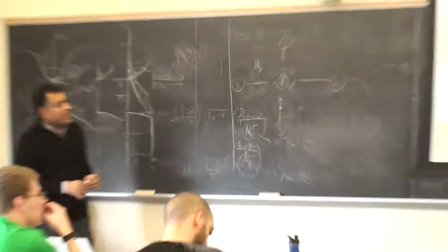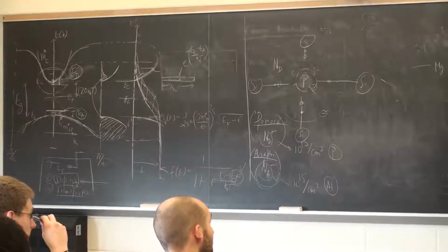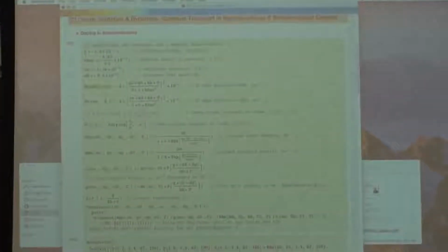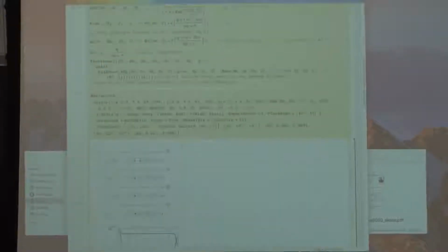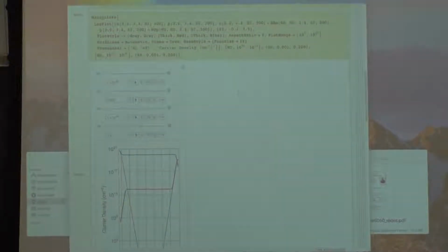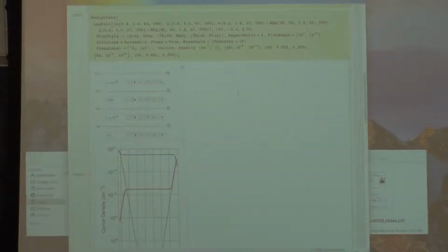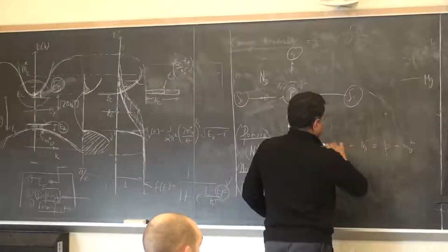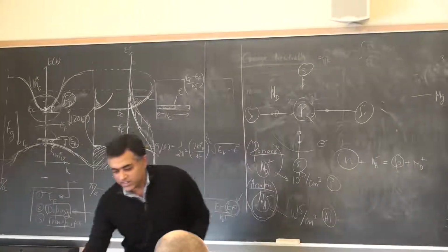One of them is a very deep activation energy, and you can set it up with ND, NA, and so on. Now for any general semiconductor, I can say, plot me the following things. I have 4 terms here: N, P, Na minus, and Nd plus. I can plot N and P as a function of where the Fermi level is inside the material.